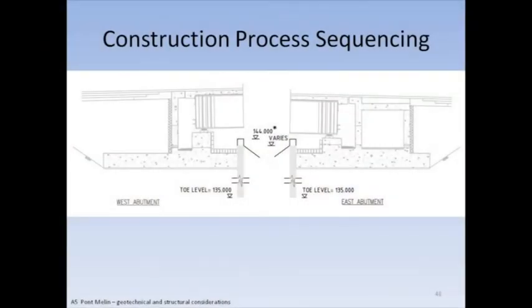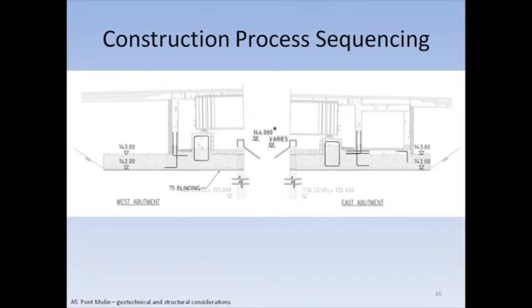So I hope this appears on the screen. It's slightly grey, but this is the construction process that Sergio described. It started off with the sheet piles being put in for the scour wall, and then the deck to the bridge cast in a conventional manner.